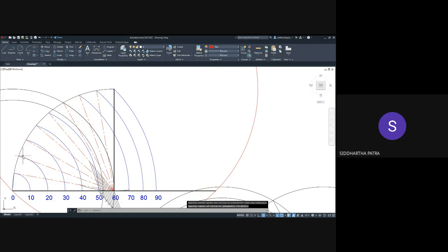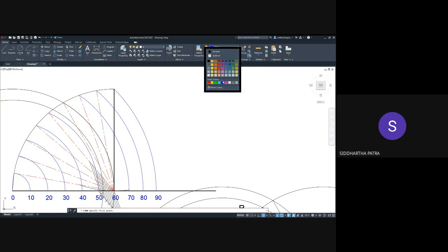So basically I'm talking about the length between this point which is marked 0 and any angle. So if you take this much of radius, that corresponds to the chord length corresponding to 20-degree angle. This is the chord length. The straight line right here is the chord length corresponding to 30-degree angle. So taking this much as a radius, make an intersection on the horizontal line.